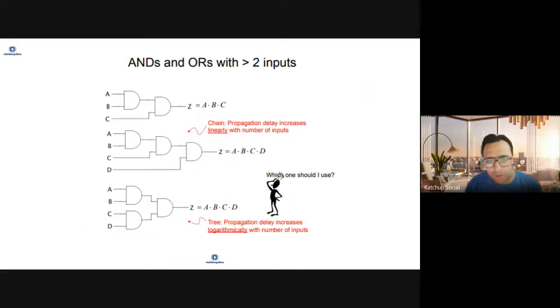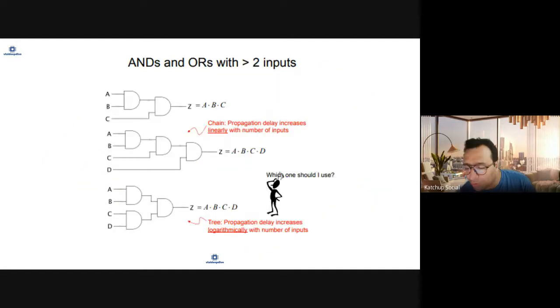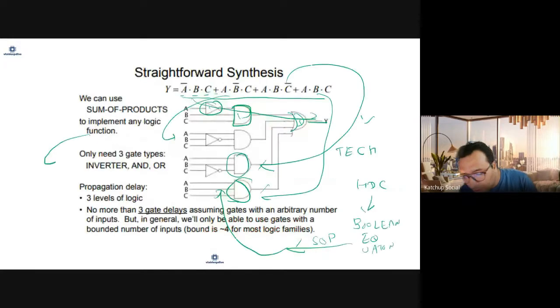Now this is assuming what kind of cells are present in the design. So here we thought of an example where 3 input cells are present, but let's say your library does not have 3 input cells. Then to represent those, the synthesis tool will have to use 2 input cells.